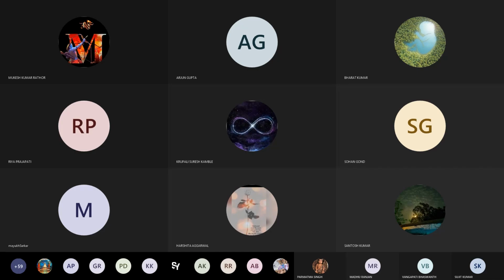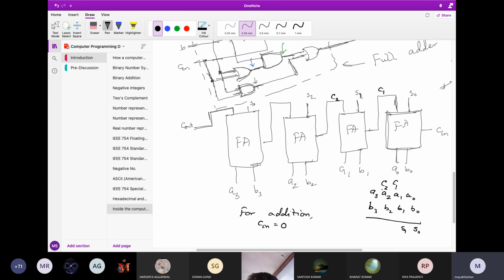So this S1 will create the carry out bit C2, whatever carry out comes out of adding A1, B1 and this C1. This C2 becomes the carry in for the A2 B2 bit, that gives me the sum bit S2 and the carry out bit C3, which comes as the carry in for the A3 B3 bit here, and eventually we get S3. That is this S3, this one.